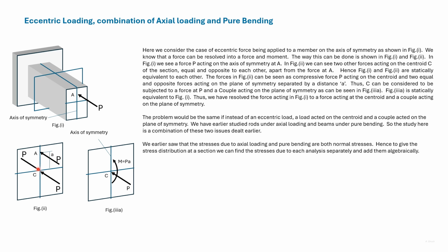Now these two forces can be considered as a couple. So these three forces can be considered to be equivalent to a force P acting on the centroid and a couple PA. As mentioned earlier, an eccentric load can be seen as a combination of an axial load and a moment. This case and this case are statically equivalent.